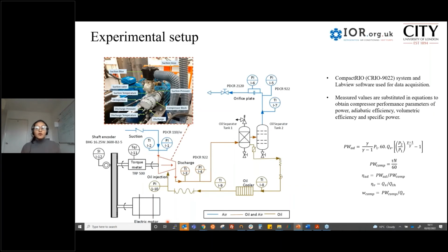We also have to remember here that the interaction between gas and oil is a two-phase flow. So we had to run through 3 different multi-phase flow models. From those, we found that VOF is the suitable model because of its lower solution time as well as the accuracy that it gives compared to the Eulerian and mixture models. So the VOF model was chosen, and we have a publication based on that, which I can also share later if needed.